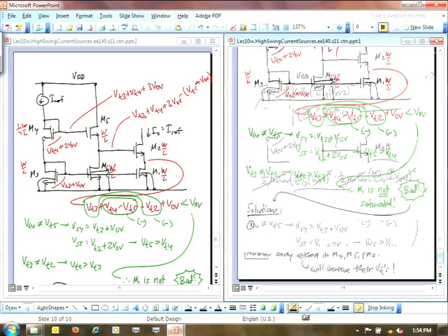Okay? And if I wanted to do this, say I wanted to make it just this voltage right here, then you can do that exact analysis that we did, and you'll find that what you need is that W over L4 has to be 1/9 W over L1. Okay, that would do the job for you, but basically all you're doing, whereas device 1, because of the strategy that we're trying to do to give us maximum output swing, has just one VOV across it.